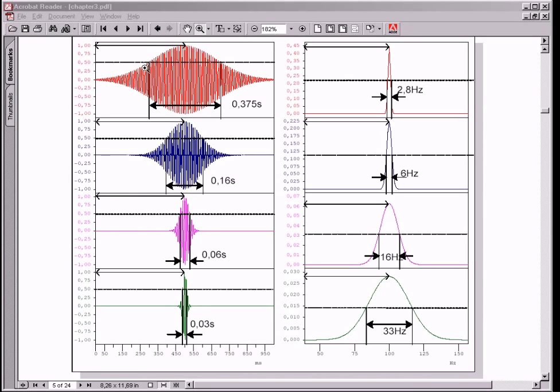If the time duration delta t and the bandwidth delta f relate to the two threshold values at which the maximum functional value has dropped to 50%, the product of delta f times delta t is roughly 1. But as the bandwidth delta f is a question of definition, an inequation is formulated which permits an estimate. And that's really all we want to achieve.